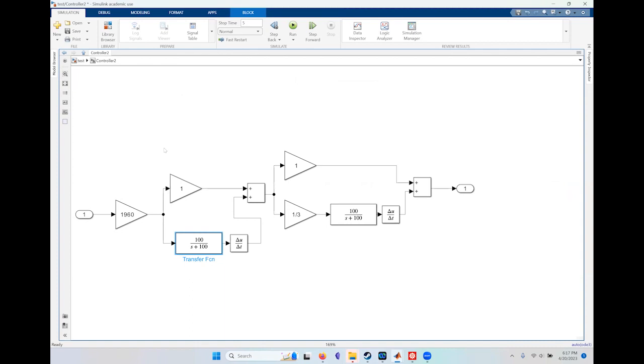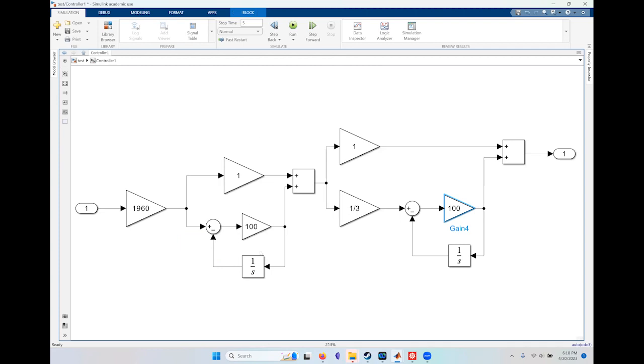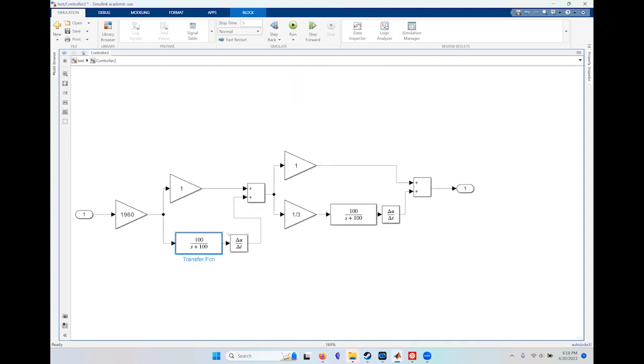because this is, let me phrase it this way, a numerical simulation that instead of solving everything analytically all at once, like we do when we do analysis, is going step by step and signals are propagating, right? And in analysis, the whole feedback loop is solved all at once. You find the analytical solution all at once. In a simulation, signals propagate through the loop, and it does matter. This is a sign of nonlinearity, by the way. It does matter only for the simulation where the signals propagate first.